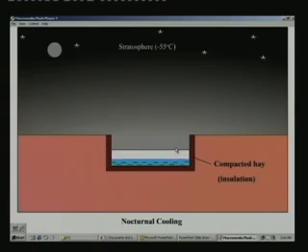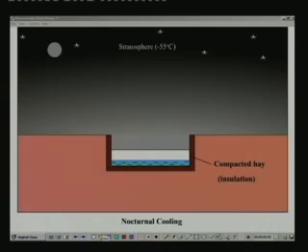centigrade. Surrounding air and the earth cannot act as heat sinks, because their temperature in tropical countries will always be greater than 0 degree centigrade. However, if the sky is very clear, then the pool of water can lose heat by radiation to the stratosphere, and the stratosphere is typically at a temperature of about minus 55 degrees centigrade. So it is possible for the temperature of water to go lower than 0 degree centigrade. This is the principle behind nocturnal cooling.